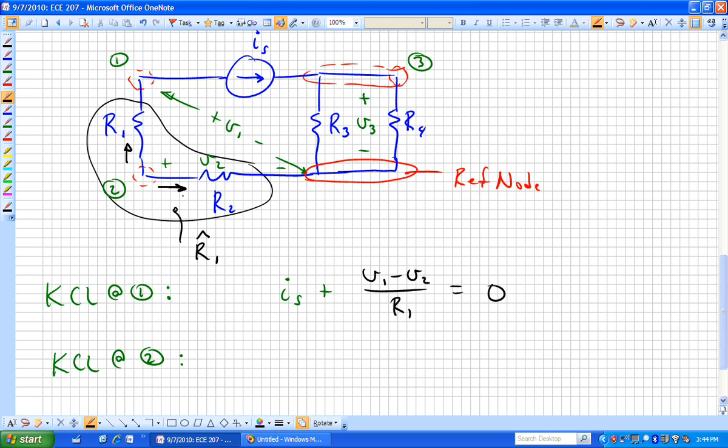Right now what we're doing is with the reference node, we're using that to be our negative sign on all of our node voltages. And then we go to each of the other nodes, and that becomes our positive sign. Put your blinders on or cover up all the current sources. Don't worry about how that's connected or related to the polarity labels we're assigning to our node voltages. Does that help?